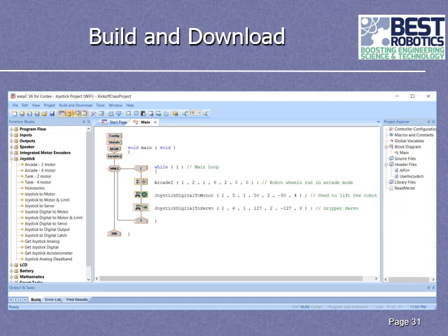So now that you've hooked your computer to the robot, whichever method you choose, now you have to initiate the build and download. There are two ways of doing this. One way you can select the menu item, build and download, and go through it that way. Or you can hit the icon. I prefer to use the second row with the icons because it's a one button push for all of these things, and the function occurs. You don't have to traverse menus, but you can certainly do it either way that you feel comfortable with. So select build and download.